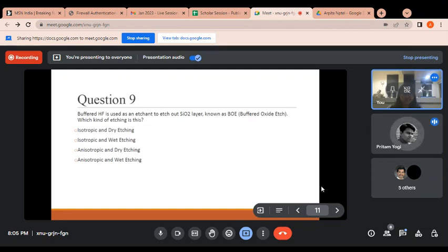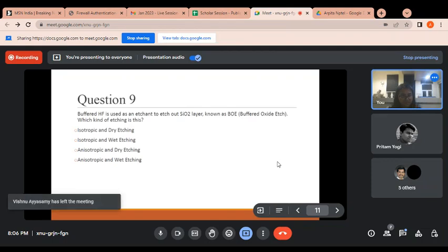Anyone else? Silicon oxide is hydrophilic, I think. It attracts water. So that's why we are now using the purging of N2 to dry this wafer. There is a difference between hydrophilic and hydrophobic. We have to see, because if there is a drop of water, we have to remove it, because it attaches to this wafer and leaves a spot. Yes, that's why we purge the N2 gas, to remove this water drop from the wafer.